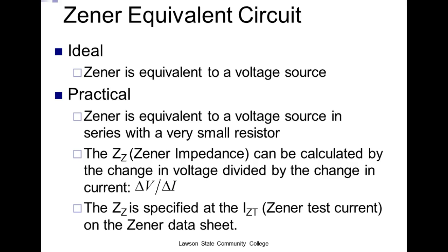They're going to be connected in parallel with the Zener. So whatever voltage is being, and what's the same in a parallel circuit? Voltage. So if the Zener's dropping 5 volts and we put a resistor across it, it's going to drop what? 5 volts. So basically the Zener becomes the source of the current for the rest of the things in the circuit.